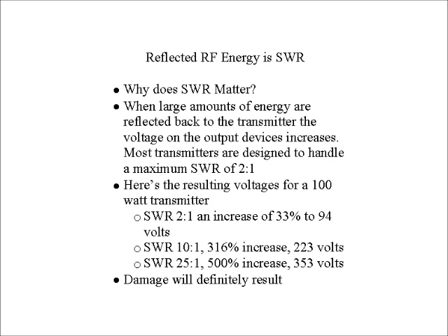What is impacted by SWR? It's your transmitter. When large amounts of energy are reflected back to the transmitter, the voltage on the output devices increases. Most transmitters are designed to handle a maximum SWR of 2 to 1.